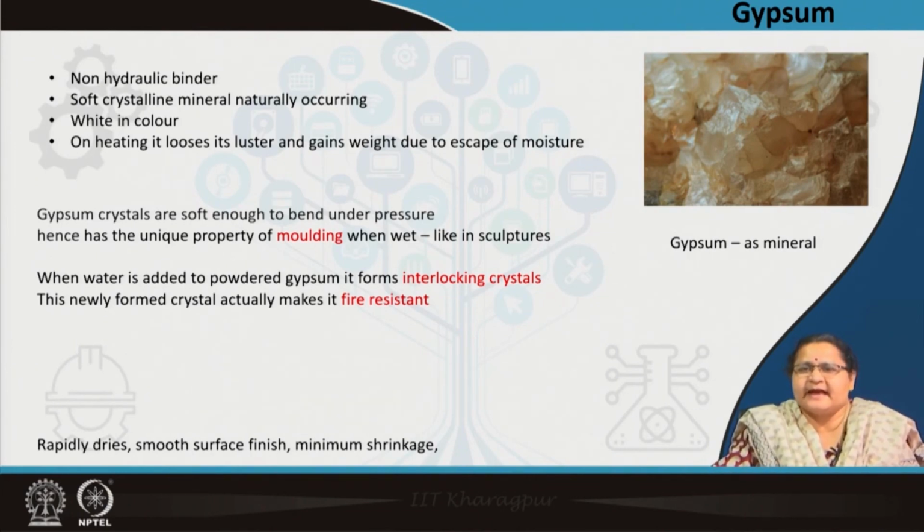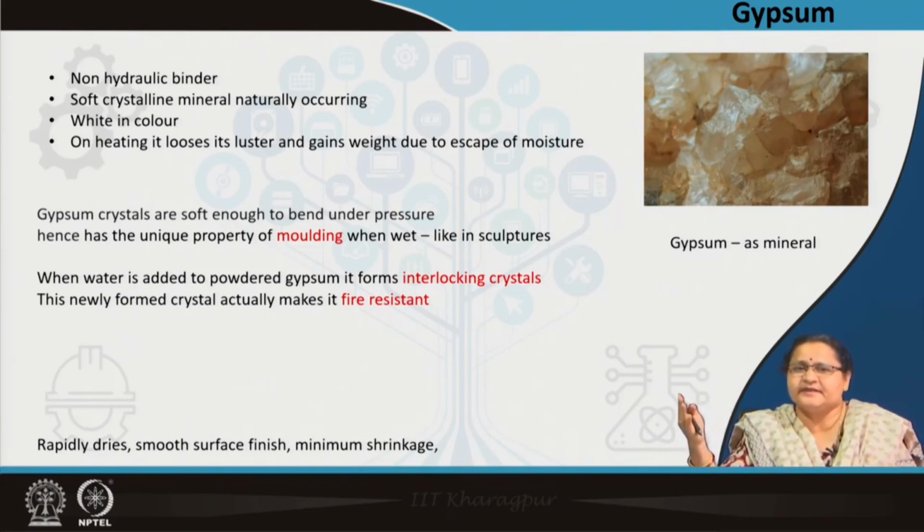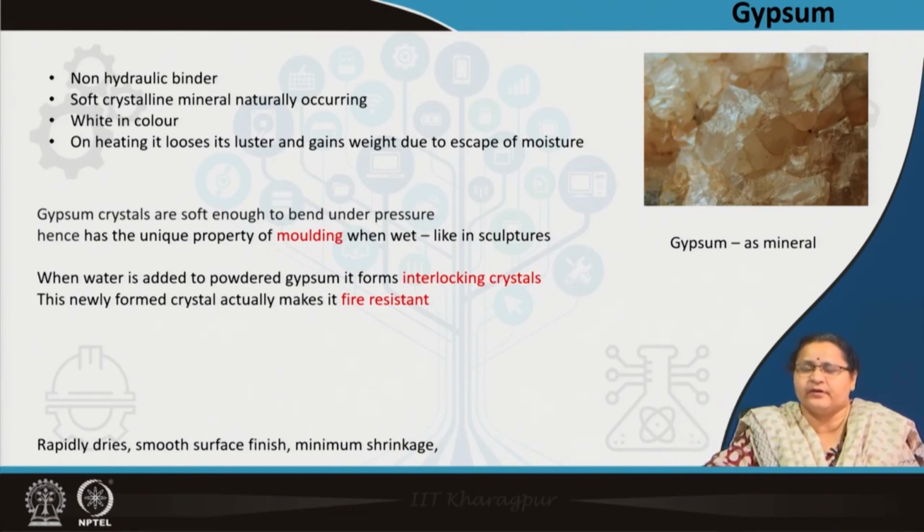So, when water is added to the powder, it forms an interlocking crystal which is fire resistant. When we were putting the gypsum board in front of a thermal insulator embedded inside, sometimes the thermal insulator may itself be a fire hazard, maybe inflammable. So, to protect that, the gypsum board is acting as a barrier.